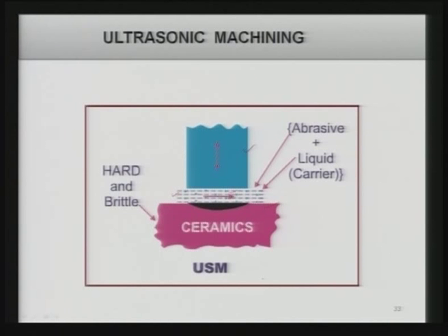As a result of that, you get a crater formed over there, and this crater is more or less of the same shape as the shape of the tool. So, you can use this phenomenon for removing material from very difficult materials like ceramics.